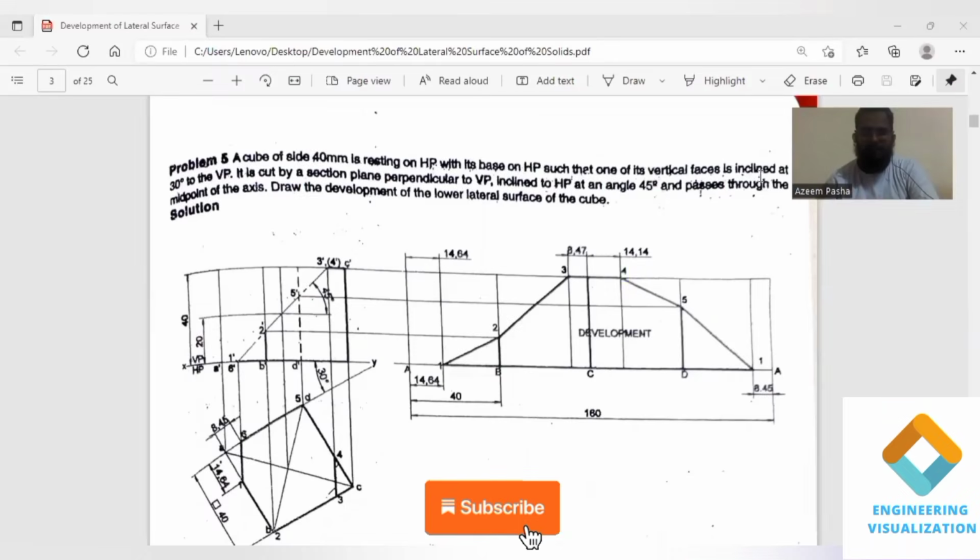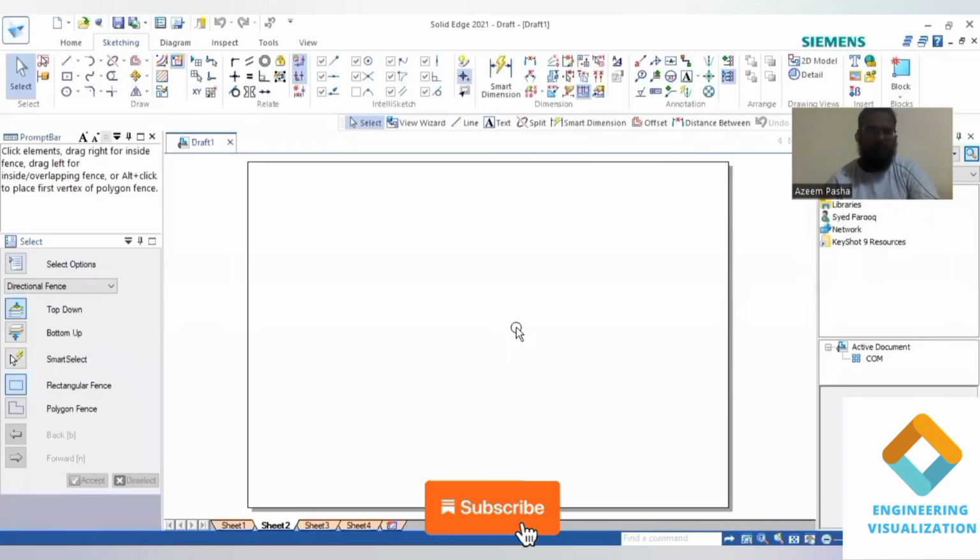You can see in this problem there is a cube of dimension 40 resting on HP with its base on HP, such that one of its vertical faces is inclined at 30 degree to VP. That means we have to draw 30 degree, then place the square of dimension 40 on it. It is cut by a section plane perpendicular to VP and inclined to HP at an angle of 45 degree, passing exactly through the midpoint. If the length is 40, we have to take 20. Then at the midpoint we draw the 45 degree section plane here, and we need to draw the development of the lower lateral surface of the cube.